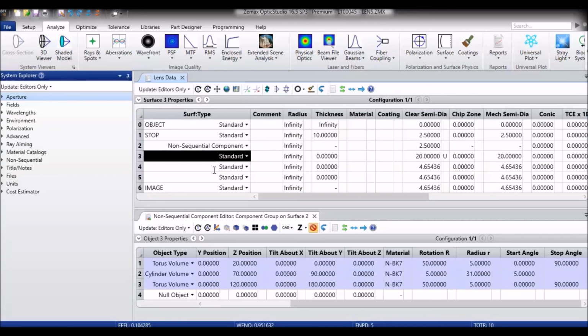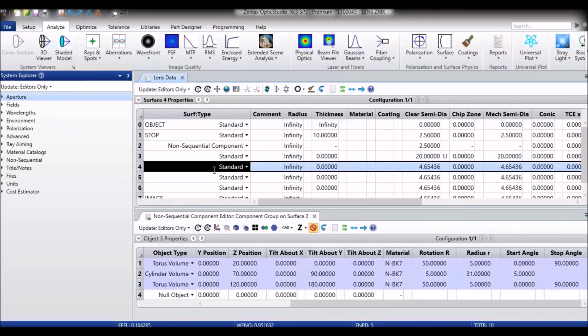You can now use any type of lenses or gratings, but just to make it easy for myself, I'm just going to put in 2 paraxial lenses, one to roughly collimate the light after the light pipe, and then one to focus it down before we send it through a prism. So again, I'm going to insert a couple more surfaces.